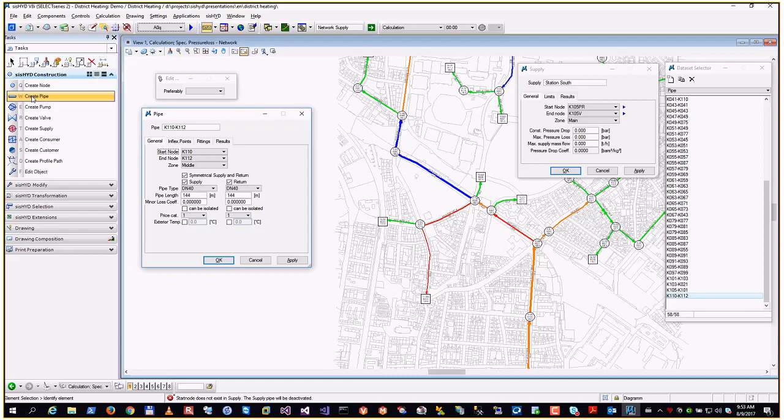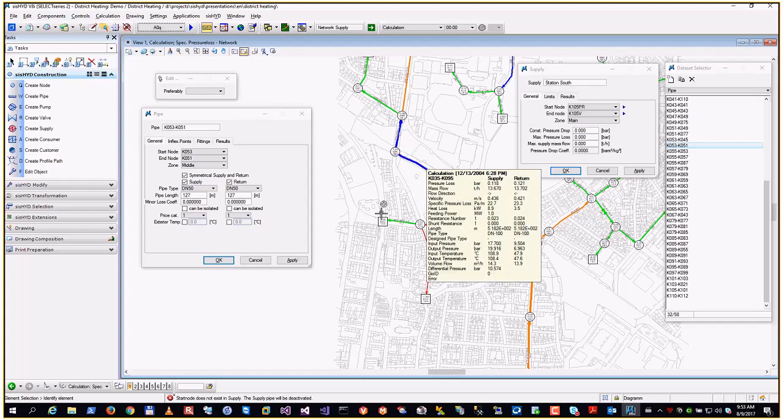And you had the question at the very beginning, how do I keep the diameter at DN300 when I do the piping for the house stations, for example? And the recommended way for it is when you start with a pipe that is on DN300, or let's say we want to now construct a pipe here with DN50. It splits the pipe and goes here to the end.